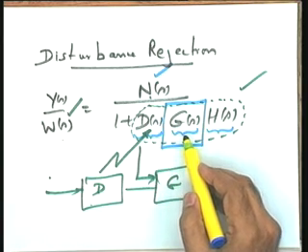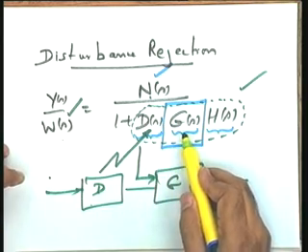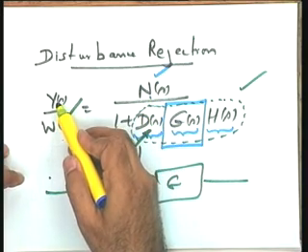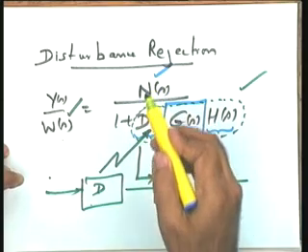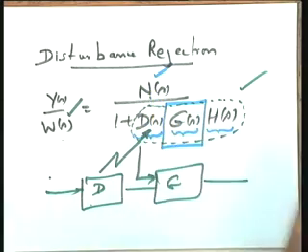So it may happen that if you change the loop gain through G, in that particular case it may increase the disturbance effect on the plant, because this G is affecting N(s) also, and this N(s) is appearing in the numerator.